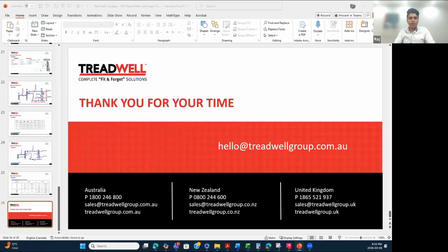It's very similar to every other FRP application where, to get a good sense, one doesn't really need to just take the material cost, but rather have an overarching view of the project cost, including the installation cost and the design life advantages that FRP offers. So broadly, let's say a structure which has a 50-year design life with a conventional material versus with FRP as embedded reinforcement, which can exceed up to 80 years. So there are benefits in the long term, if that answers your question.